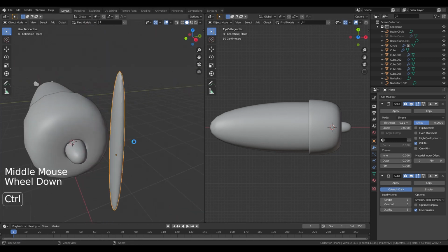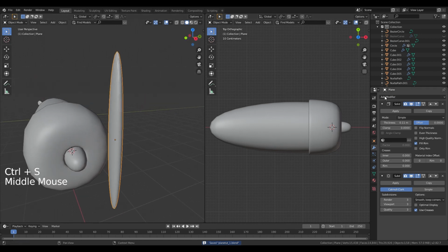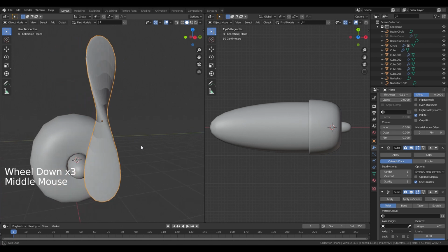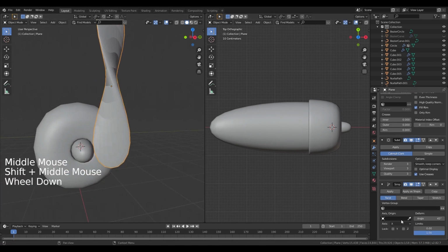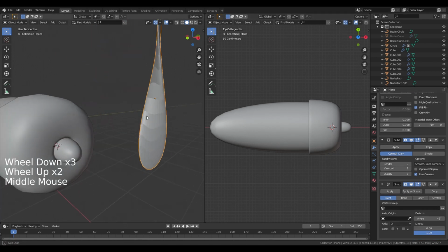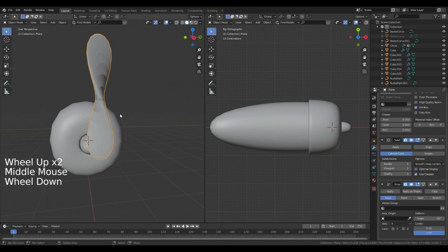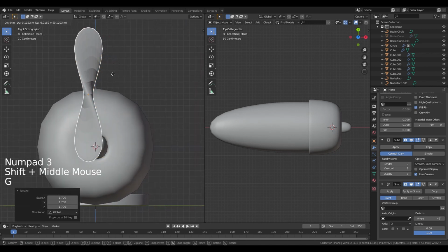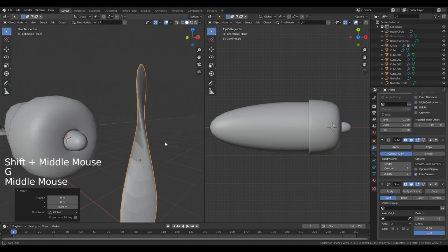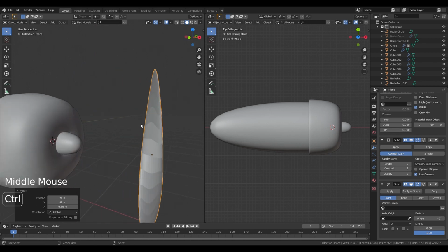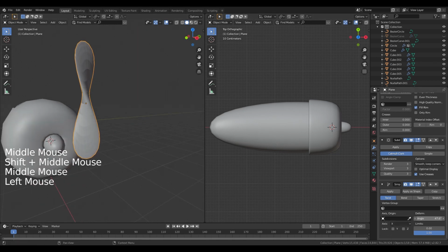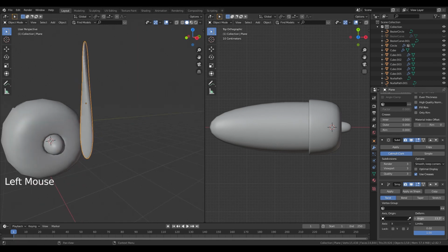I want to add a simple deform. And this is actually what is going to give us our propeller shape. Now, one thing you can do is just keep with this propeller shape. So you could just scale it up, go into side view, and then match it to your propeller, see what the height is. But we want to have 3 propellers, for example. How do we solve that problem? Well, first of all, I want to create this propeller to have a nice little bend shape.